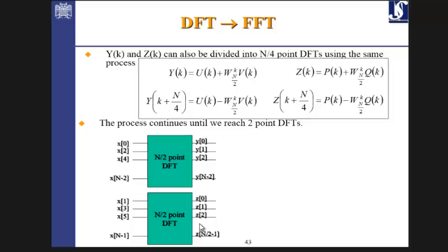Some layers, division by 2, in such a way that the final result is coming back to the same DFT, but it's much, much faster. The original DFT is n squared. If n is, for example, 1000, normally we have for speech n 1024. So assuming it's 1000, then DFT of 1000 samples is 1 million. But in case of FFT, it's just 10,000. With 10,000, you can get the same result. Completely the same result, much faster, 100 times faster. And that was a revolution.